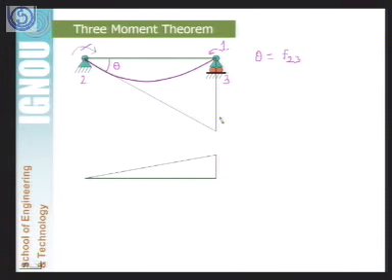And again we are going to use the same principle of the moment area method. So we will calculate the value of T32, the tangential deviation of point 3 from point 2, and that will be equal to the moment of the M by EI diagram taken about point 3. So the M by EI diagram you can see here, this will be equal to 1 divided by EI2, the length is L2, this is node 2 and this is node 3.